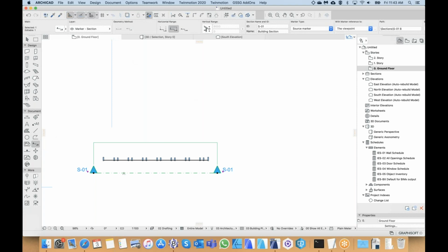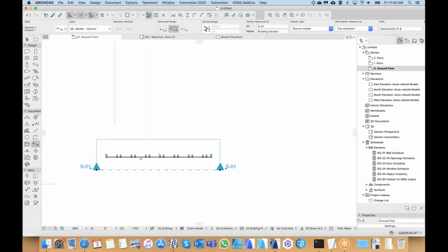So we've just drawn a section line in front of the curtain wall. We include the entire curtain wall and a limited depth, just so we can see this enclosed. Let me know if you've got a section line in front of this curtain wall, because we're going to use this section to edit and draw on this curtain wall. Done. Great. Thanks, Gary.